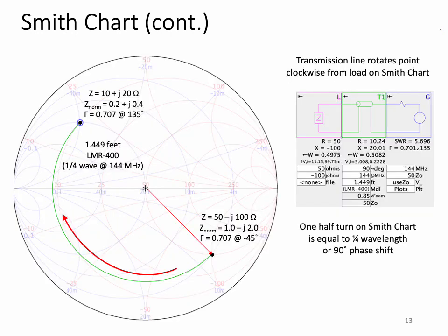Another very important feature of Smith's conformal mapping is that if I move a quarter wavelength down a piece of transmission line terminated in an impedance Z, then I rotate exactly 1/2 turn from where Z is located on the chart. So one full turn around the chart, which represents 1/2 wavelength, gets me right back to the same spot. And that's a consequence of that tangent term that we saw in an earlier equation.